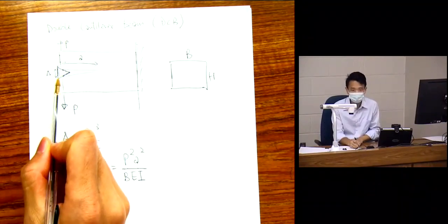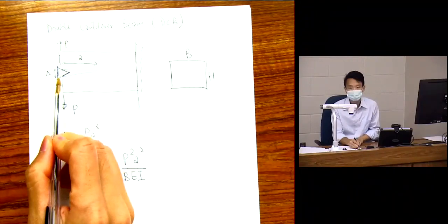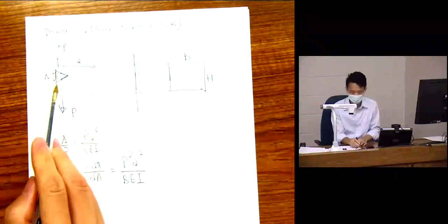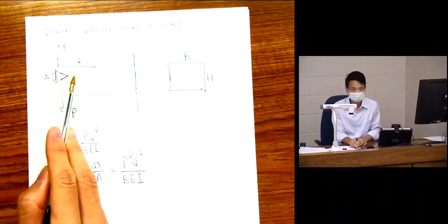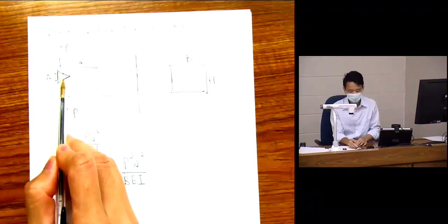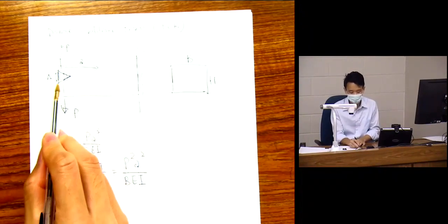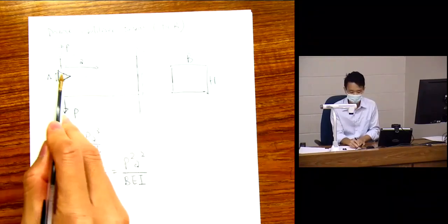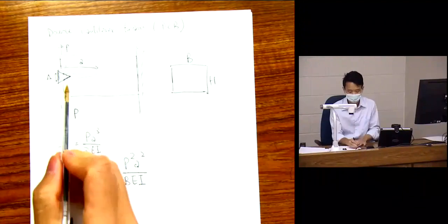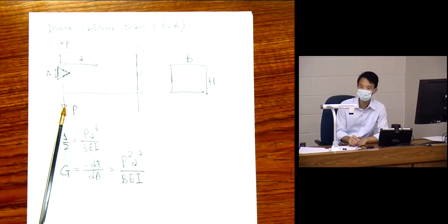The other configuration is I put a wedge. Instead of putting the two forces here and there, I just put a wedge in the mouth and I keep hammering this wedge towards the crack, and that is going to give me what? An opening of that crack, right? Because I'm trying to drive that wedge inside, and this is going to keep pushing these two slabs away from each other, and that will actually give a crack extension. Okay.